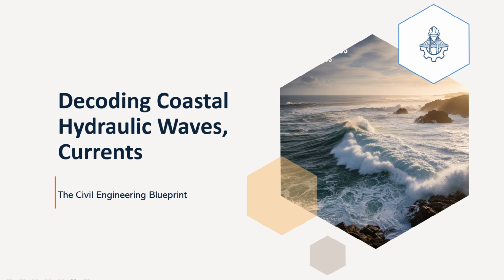The key insight here is profound. Deep water wave celerity depends only on the wave period, T, not the water depth, d. Longer period waves travel faster. This is why swell waves, which have traveled far from their generation area and sorted themselves out by period, travel faster than locally generated wind waves. Then we have the opposite extreme, shallow water waves, or long waves.